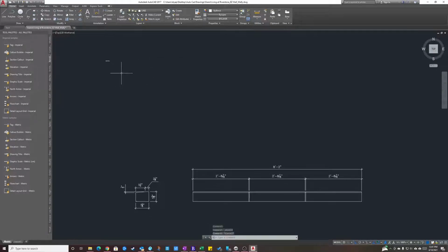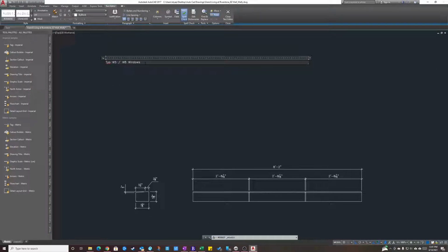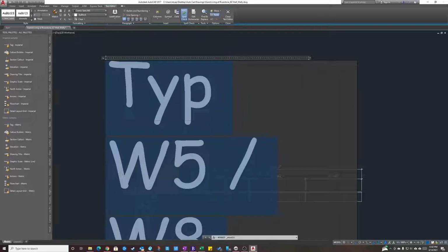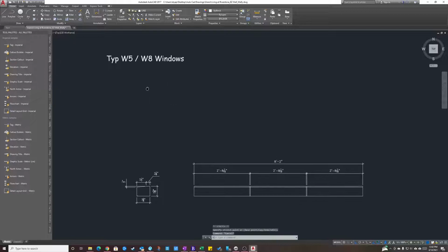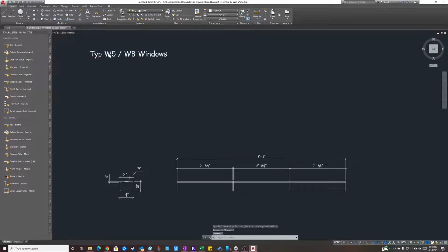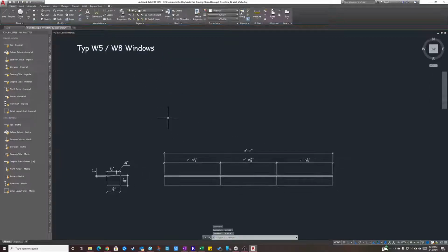Okay, well, how do I fix that? Well, you double click it, you highlight it, you go up here. These are your different types of letters, etc. Select it again. It's 1/8 of an inch right now. That's why you can't see it. So you're gonna play with your measurements. Type in 3, hit enter. Oh, it's gonna look huge. That's fine. Just click anywhere, and it'll readjust. So yeah, 3-inch letters look good to me right here.